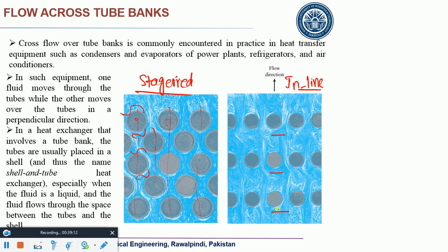Can you think of the boundary conditions? I mean, you know that on this surface u would be 0, v would be 0, then velocity would be 0 on all those surfaces. Let's say this is the inlet value. Okay, fine. We are going to have v infinity equals 1 meter per second. Fine. You can describe pressure over there, for example, in some case. How can you solve it? I mean, to solve this problem on a simple flat plate is very complex.